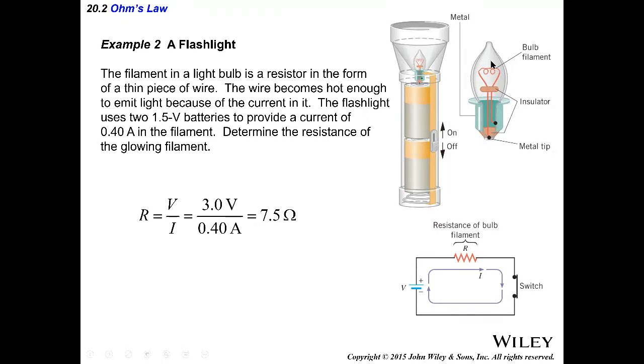But you put 110 volts on it, the current now becomes very high. And if the current becomes very high, the power consumed by this filament in the lamp is I squared R. Well, R is 7.5, but I can be like what, 10 or 20 or 50 amps. This thing would burn out. You see now how I squared R or V squared over R are very key concepts of power consumed. And in this case, this is where the filament burns up.